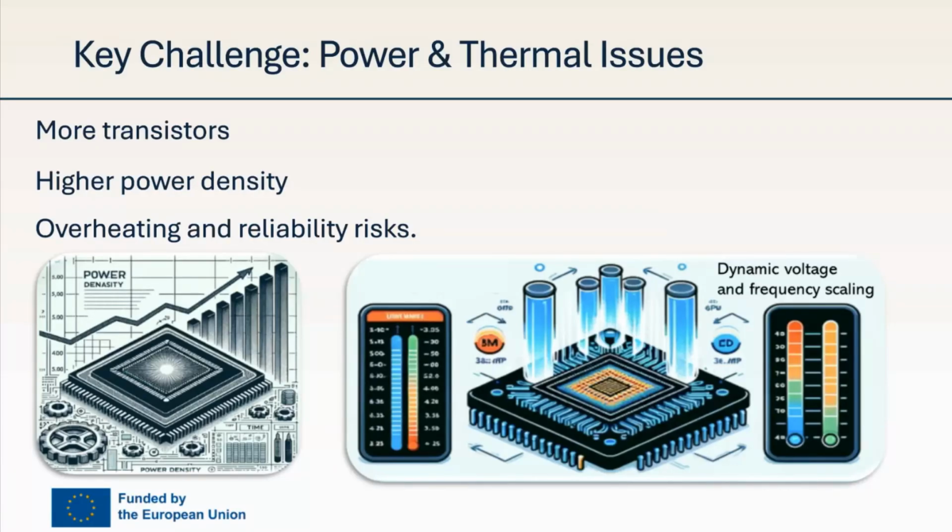This not only affects performance, but also reduces the chip's reliability, as prolonged high temperature accelerates component degradation. Traditional methods like DVFS, dynamic voltage and frequency scaling, are typically not enough to handle this challenge, especially for high-performance designs, necessitating advanced thermal management techniques.